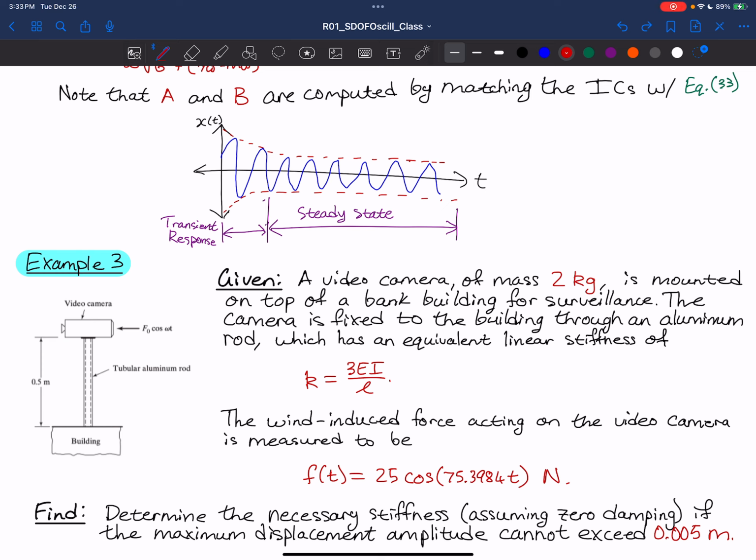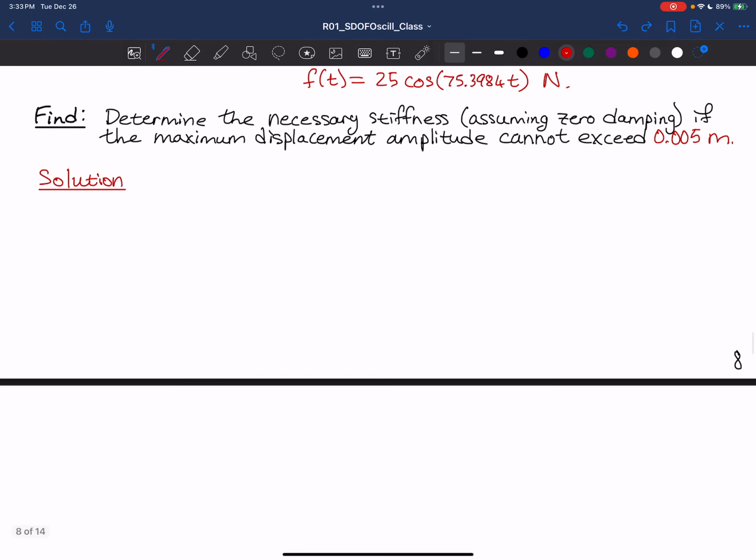Hitting a large displacement, or a relatively large displacement, once may not necessarily damage or break the system, but sustaining that large amplitude for a long period of time can lead to early failures due to fatigue. And so that's what we're really interested in here. Okay, so in this case, we're going to say that our steady state displacement, and that's what it should say in the problem. It should not say maximum displacement. In the video here, in your notes, it will say steady state.